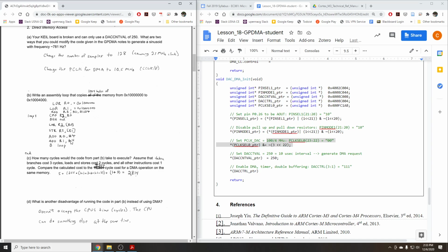So this is actually saving us a little bit of time because I'll only have to do this 1024 divided by 4 times instead. And then I'm going to jump back to the top of the loop. And at the top of the loop, I'm going to compare again. So once I do get to 1024, I'm just going to BEQ to the end. I'm going to jump out of this loop. And that's all I have to do to copy that memory.